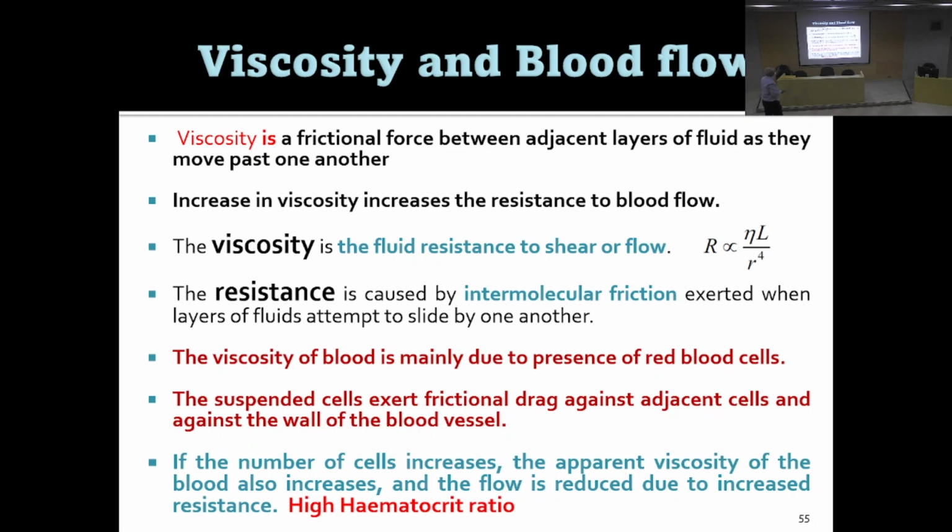Okay, so viscosity, we say this is the frictional force between adjacent layers of the fluid as they move past one another. Of course, viscosity is temperature dependent, isn't it? When you increase the temperature, viscosity goes down. When you want to pour something quickly, like honey, you heat it up a little bit to become less viscous, so more flow.